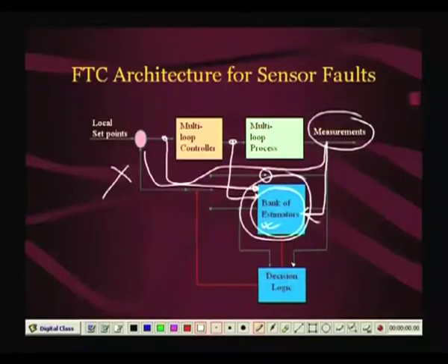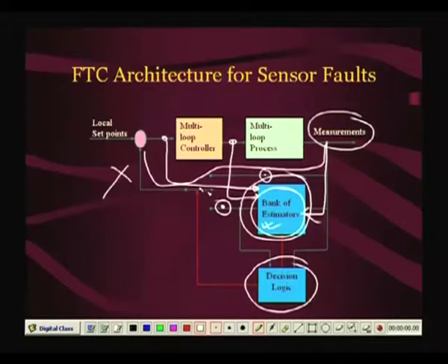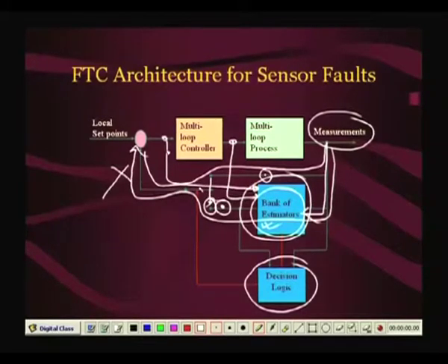So, once we can do that, then we have no problem, because if we can detect that there is a failure and if we can compute the value of this failed sensor, then we need to simply flick our switch from here to here. Now the feedback path of the control loop is going to be closed like this. The controller does not understand this difference at all, whether it is coming through this path or this path, it gets the feedback. So therefore it can maintain performance.